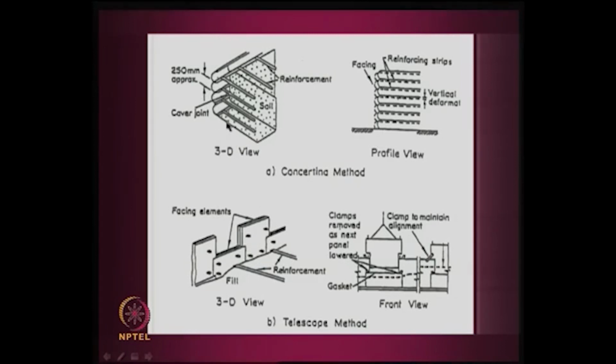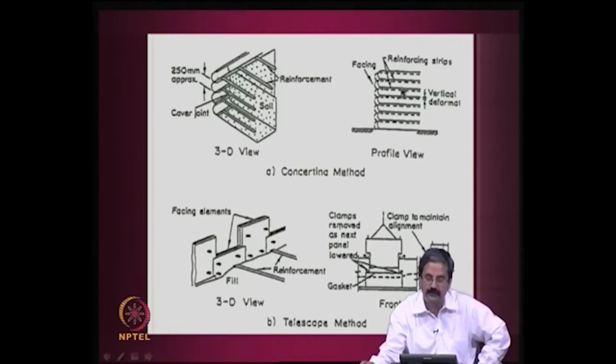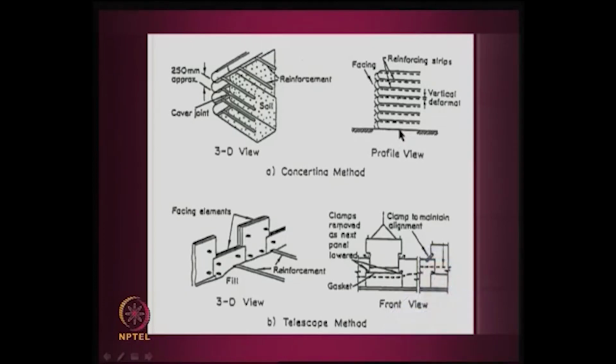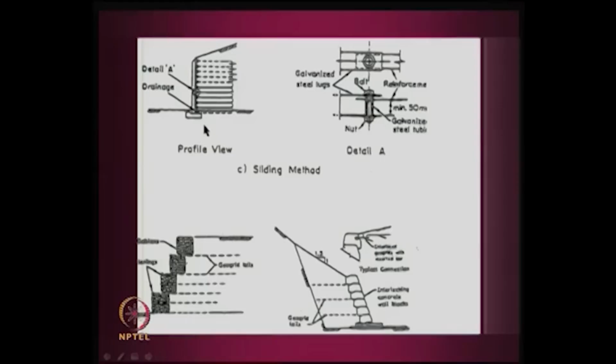This is in spacings of 250 mm, in terms of the compaction lift thicknesses, and there are different methods of doing that, and we will see more of this in the coming classes, because this is one technique that has made a very big impact in infrastructure, construction of flyovers and all that. Okay. This is another one that I would like to show. You also have some drainage elements here. This can even be a Gabion type of wall, you can put reinforcement like geogrids, which is so flexible, and in the case of slopes also it can be done like this.